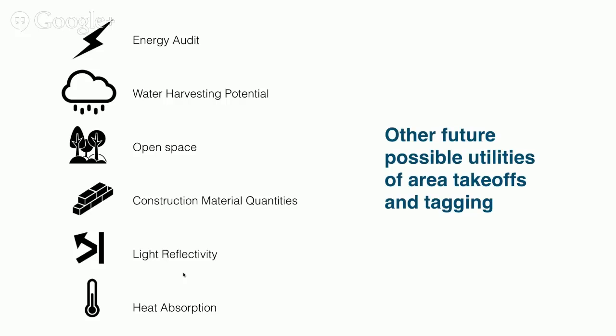So if we want to do square foot takeoffs on one level on horizontal surfaces, but also vertical surface takeoffs for construction material quantities, you assign a relationship to a cost table, and then you can connect that to the kind of analysis that Fletcher was talking about yesterday, except rather than using a gross assumption for a site, you're actually deriving the core metrics for that analysis from the geometry that you're generating.